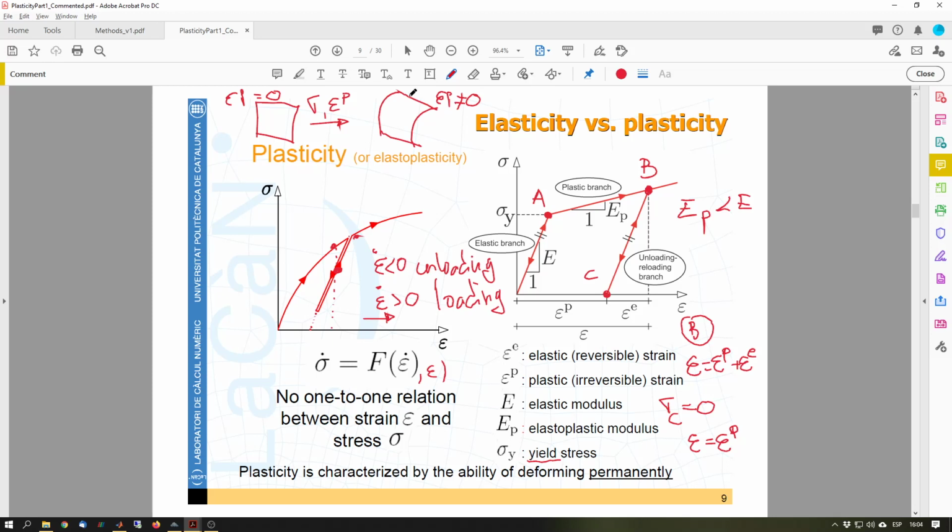In general you don't know where they are located, but what you care about in industry many times is the shape. This is what you aim for, and you also want your stresses to be as low as possible. You always want to satisfy this. We said that in statics, this divergence of sigma equals 0 is true for any material, linear, non-linear, and that's even true for plasticity.